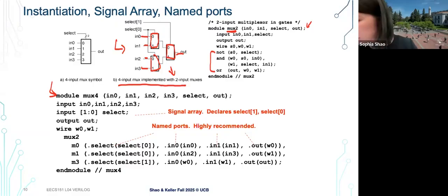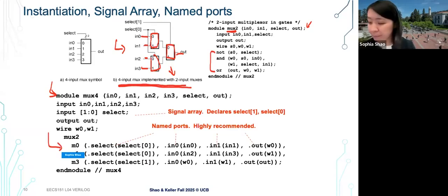So once you know how you're going to build your muxes hierarchically from 2-input to 4-input, it becomes easier to instantiate the 3 muxes we discussed earlier and match the different input and output ports to the corresponding muxes, because each of the 3 instances will have its own input, output, and selection signal pair.